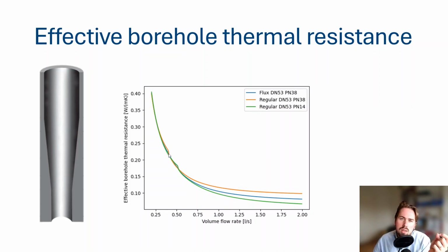But one important thing to note is that our flux probe, although it might experience a transition to fully turbulent somewhat later due to the fact that our average Reynolds number is somewhat smaller, we also have, on average, a lower wall thickness. And the wall thickness is also a conductive resistance.